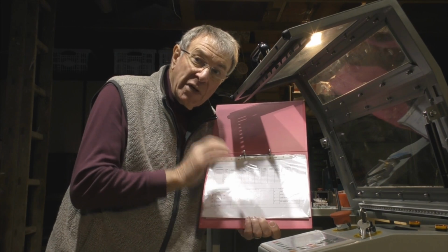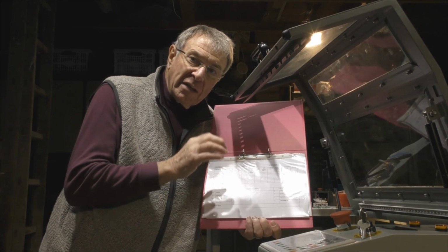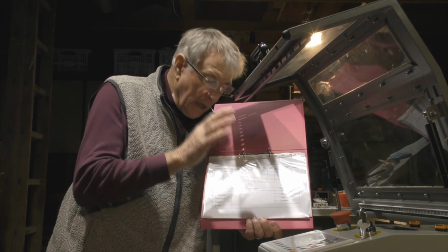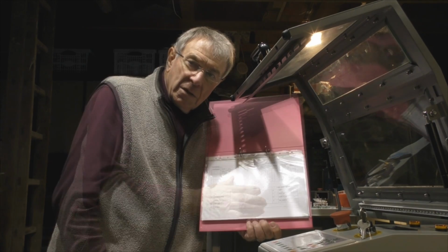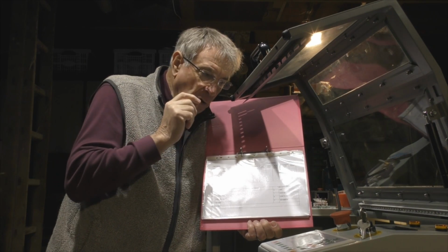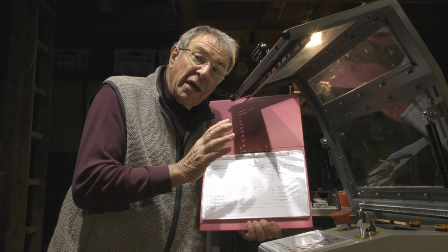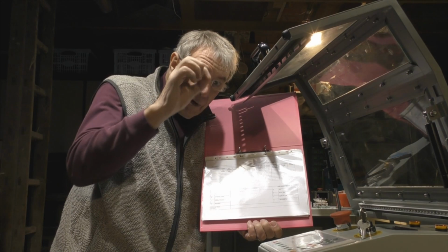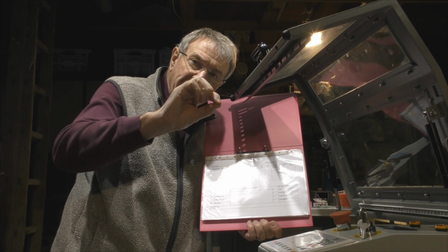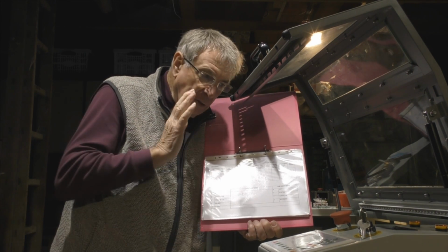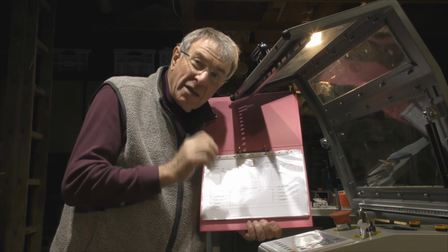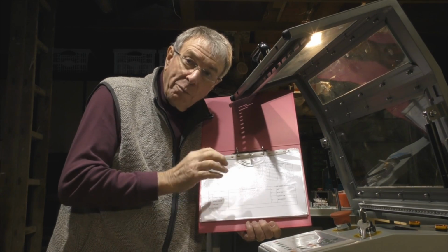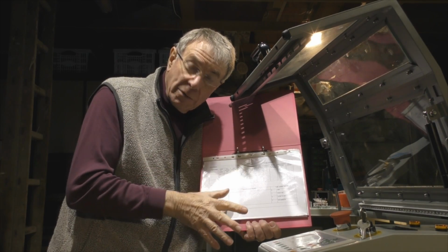Acrylic is a unique material in that it sublimates. You fire heat at it and it evaporates. Everything else burns. Now, never lose sight of the fact that your laser beam is not an innocuous beam of light. It's a very powerful beam of fire, just over the thickness of a hair. And it can do a lot of damage, but it is fire, heat, concentrated heat energy. And it will burn, and it will char, and it will smoke.